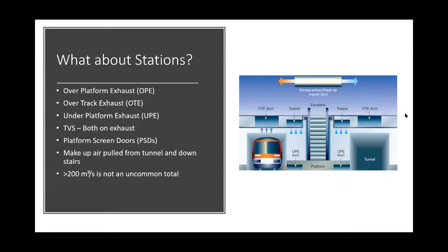The key advice I had for any fire engineer working on anything with batteries is to understand that thermal runaway and fire are not necessarily the same thing. You can have a thermal runaway where a battery gives off combustible gases and creates an explosive environment, particularly in an enclosed tunnel. Or you can have a fire that also causes thermal runaway, but in theory, a lot of those combustible gases are being consumed as well. So batteries do need to be thought of and designed for, and your ventilation system would play a part, if you have a disabled vehicle with a battery in that thermal runaway mode.